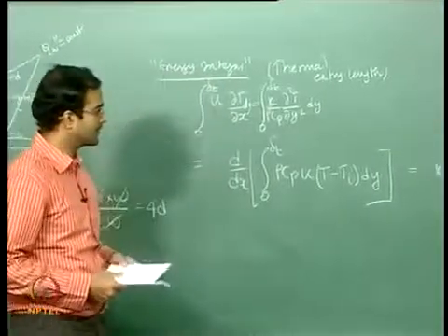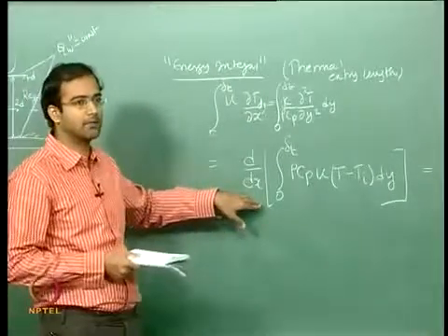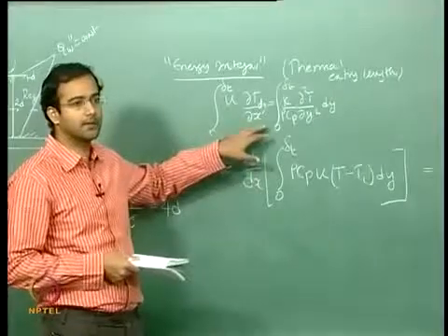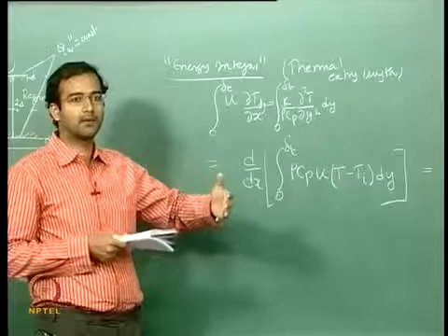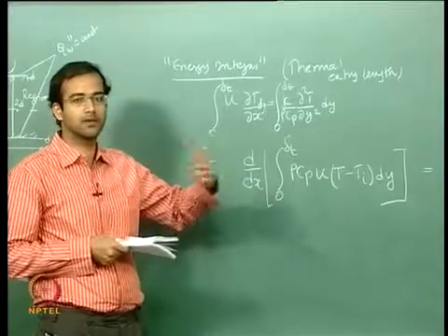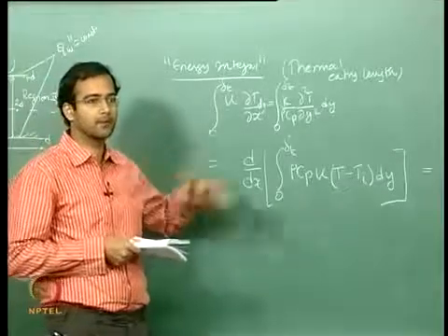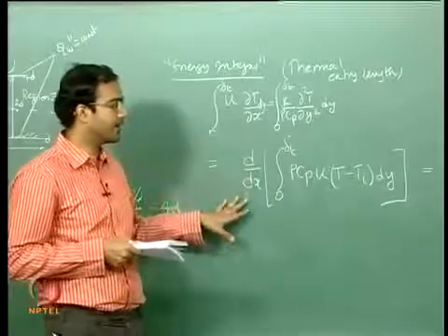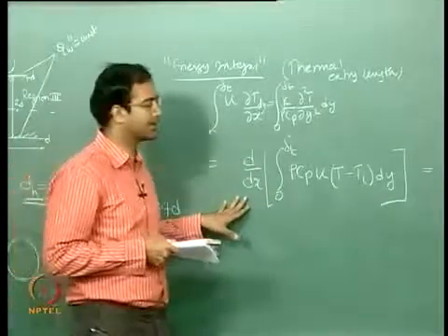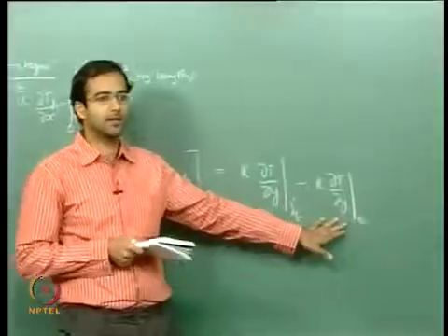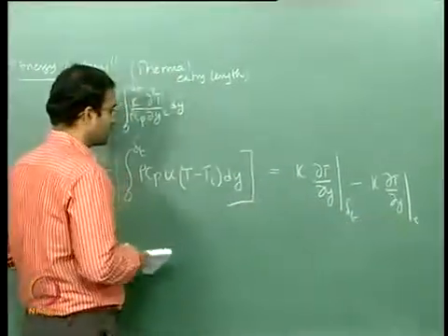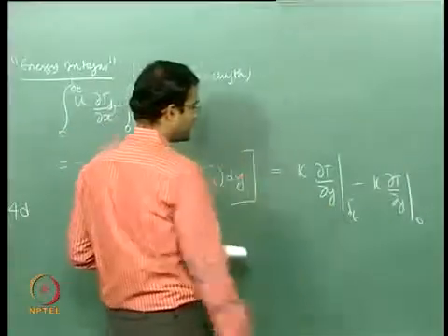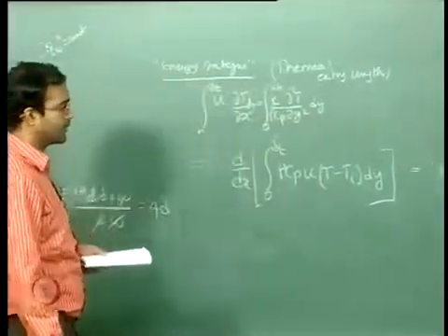Okay, so this is very similar, and in fact it is simpler than the flat plate case. There I had a v dT by dy, and I had to rewrite my v in terms of u and convert all my derivatives in terms of derivative with x direction. Now I have directly only a derivative with respect to x direction here, and this is of course related to the wall heat flux, okay, which is known. So what is the value of k dT by dy at delta t?